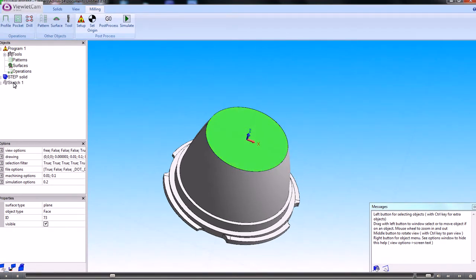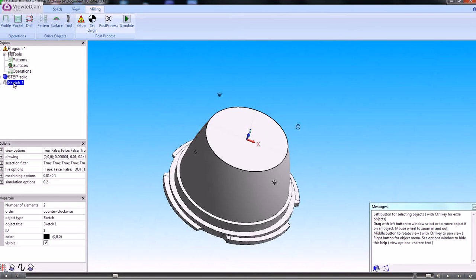So that's now made a sketch, which is just a 2D shape which we can use as the inner boundary for the 3D pocketing command. Now the 3D pocketing command will only take place around the cone, but I need to create a sketch of the base of that, which will be useful. I could use the face here, but that would give me a sketch which was the exact size, so we want the sketch to be bigger than the size we want.